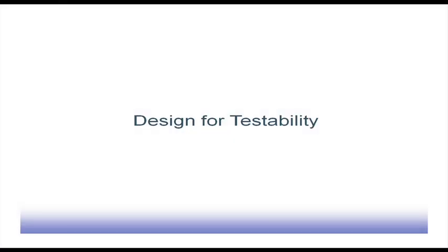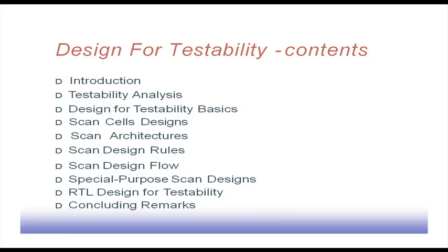Next we will look into the topic design for testability and the issues related with it. As we have seen in our last lecture, design for testability is a very important part, as it enables easy testing of the system. If we want to enhance the testability of a system or circuit, we have to put some extra hardware into it, so that this testing can be done efficiently.